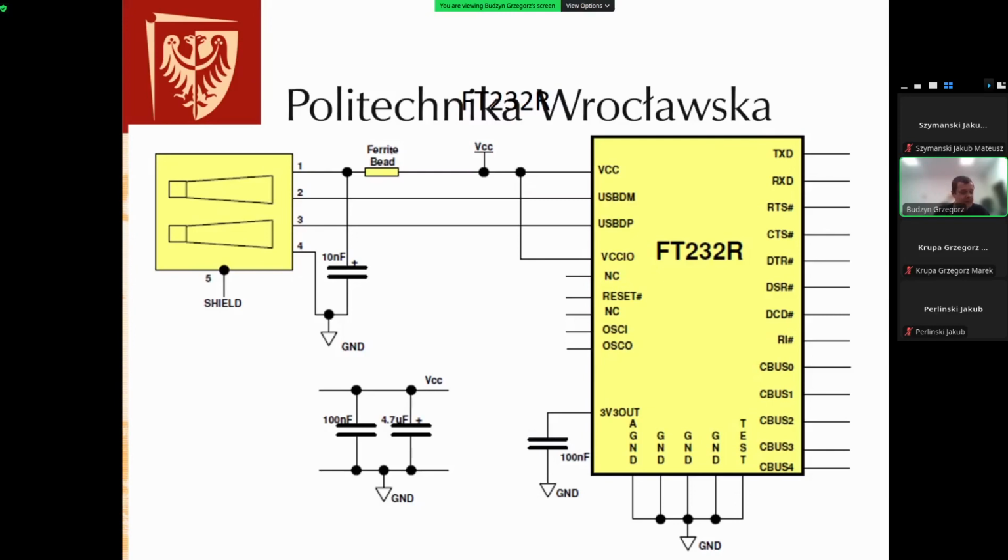The USB bus, the standard one, again, small reminder, there is a requirement of at least 4.35 volts as the VCC value, with current capability of 0.5 amp. So it's slightly more than 2 watts of available power, which is a lot for supplying this kind of chip.